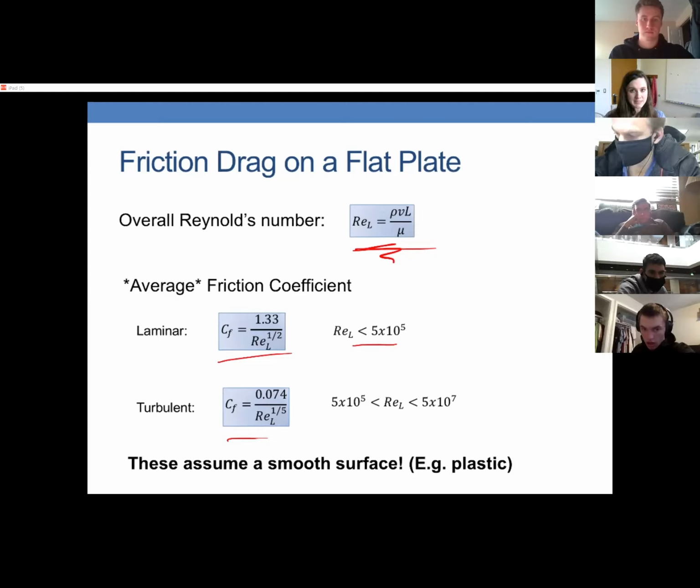So that assumption means there's a laminar part at the beginning and then a turbulent part. So it kind of has to be long enough that the laminar part is small and becomes insignificant compared to the turbulent part. Sometimes it'll be in between and things get more complicated. But if it's long enough and the Reynolds number is big enough, we assume it's turbulent over the whole thing. L is length. So L is just the length of the whole plate.